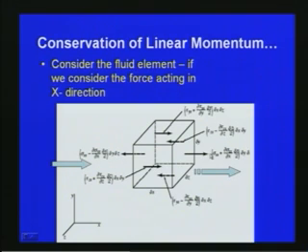And then similarly, on the opposite side, the other side of the fluid element, we can write the normal stress. With respect to normal stress, the surface force can be written as sigma xx plus del sigma xx by del x into delta x by 2, into delta y delta z. So this is as far as the normal stress is concerned.